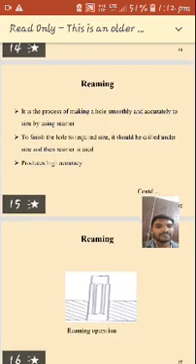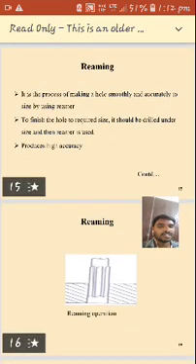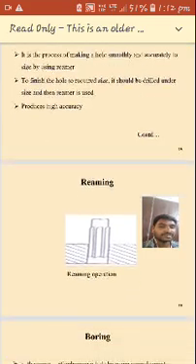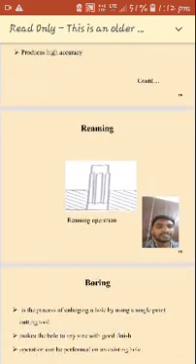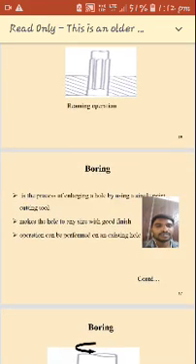After performing the drilling operation, we can go for the reaming operation. That reaming brings the hole to the exact size by removing a small amount of material from the hole. By using that, it produces high accuracy. So the reamer tool is used to perform this reaming operation.